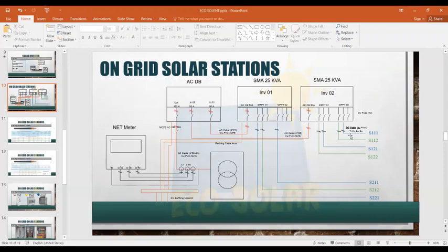This is the DC input. Then getting out from the inverter by AC circuit breaker and AC cable, red color. This is the first inverter, and this is the second inverter, across the MDB that we will see a few pages later, the detailed main distribution board. 2 inputs on circuit breakers and 1 output circuit breaker going directly to the power transformers.